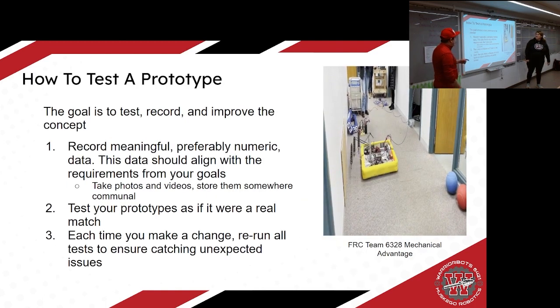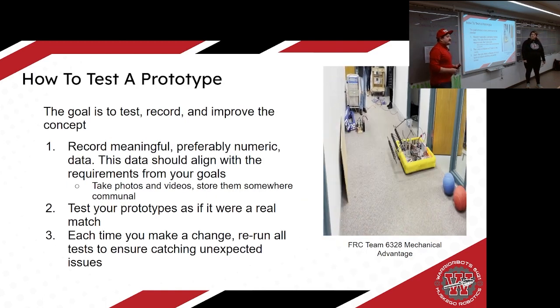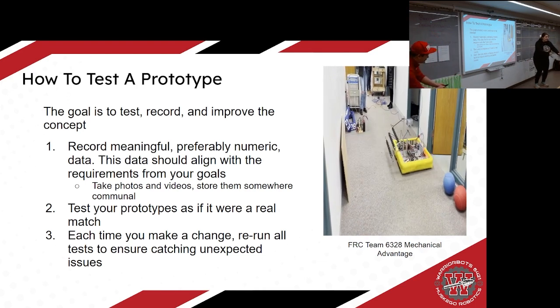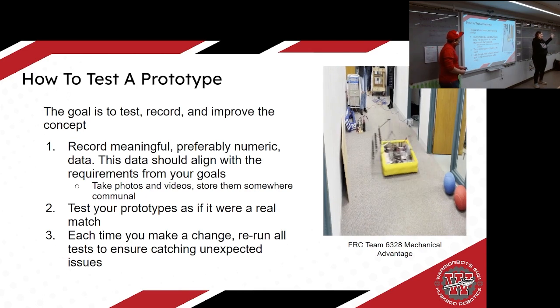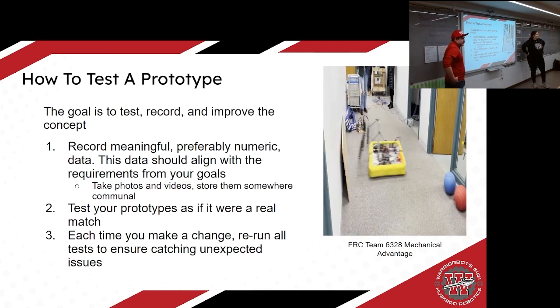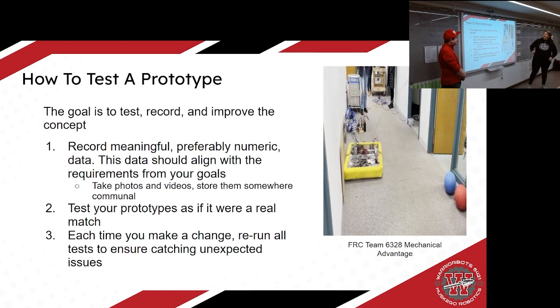How to test. When you're testing, make sure you're testing realistically. One of our favorite examples is when you've just built your brand new intake for your robot and you daintily, gently roll a ball at the perfect speed and angle into it, and oh my God, it grabbed it. That's amazing. That's not realistic. That's never going to happen on a field, right? Probably, unless you got a really good human player.